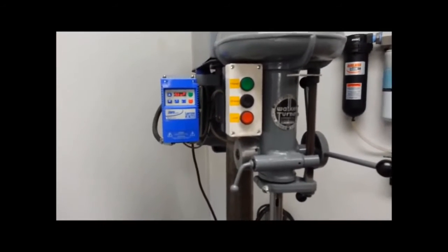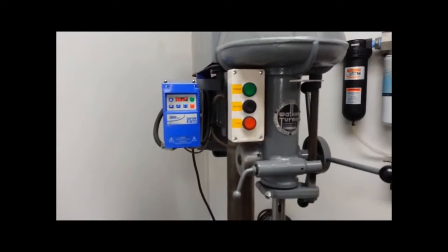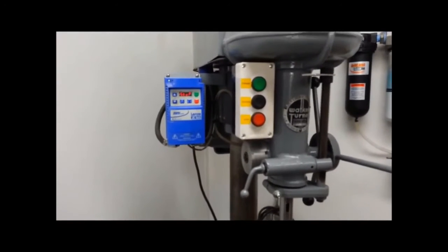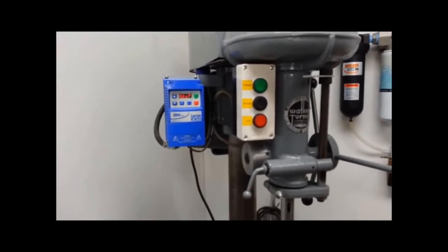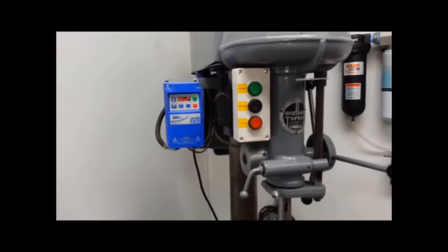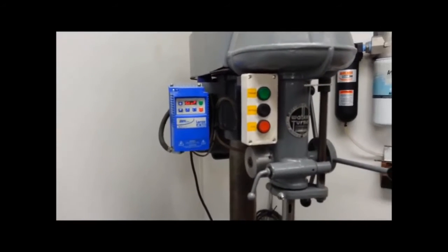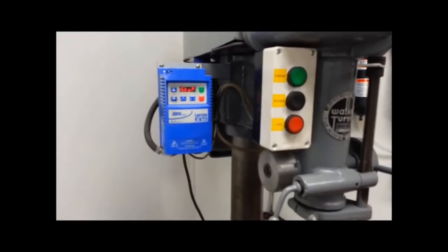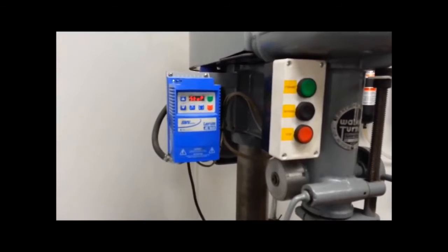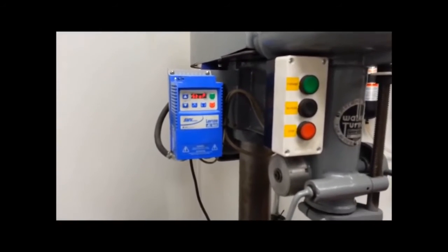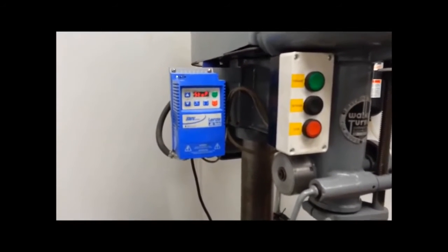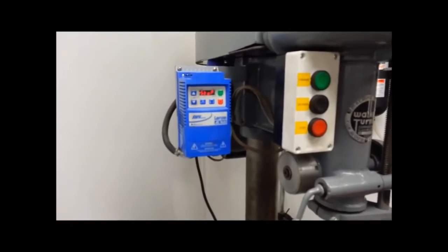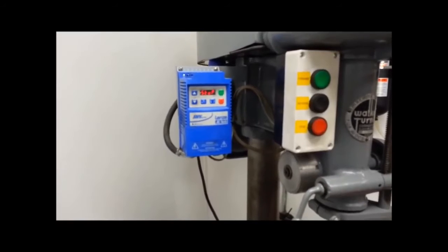What you want to do with those is, if you still need, say at the lower RPMs, a bunch of torque, but say we want to exceed 1,700 RPM on the motor, this is usually easily done. The rotors inside of a 4-pole motor, which is 1,700 RPM, are identical in every way to the rotors inside of a 2-pole motor, which is the 3,000 RPM.